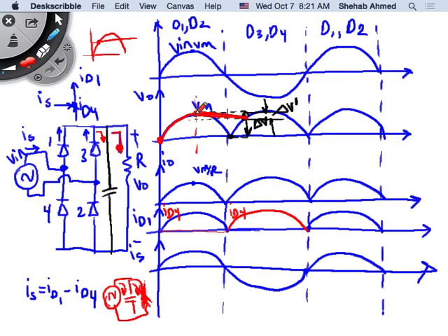Conduct means current is coming from my source. I have current coming from my supply. And current coming from the supply, if the supply is a sinusoid, remember, capacitors and inductors, what would they do? They shift by 90 degrees, right? So if I'm applying a sine wave of voltage, IC equals C dVc by dt. It's the differentiation of voltage. So you shift the voltage by 90 degrees. The current in the capacitor will lead the voltage by 90 degrees.